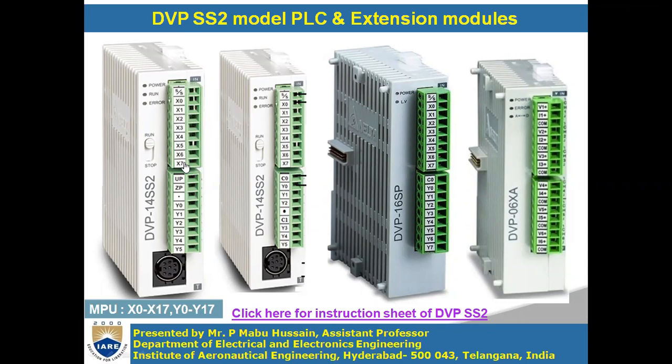X0 to X7 are the digital inputs. Okay, in total you have 8 digital inputs, and Y0 to Y5 are the digital outputs, and in total you have 6 outputs. So 8 plus 6, which is 14. So right, this 14 represents the total number of input and output points, you can also say terminals.